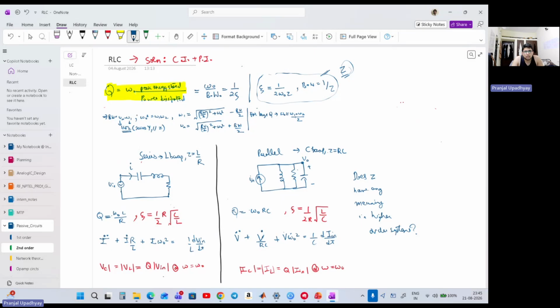So here, again, my shortcut or mental model was: in the series circuit, the inductor is the buff, and in the parallel circuit, the capacitor is the buff. Why I said that is because this tau term that I have defined is the time constant of a first order circuit. So for series we use the time constant corresponding to an RL circuit, and here we'll use the time constant corresponding to an RC circuit.